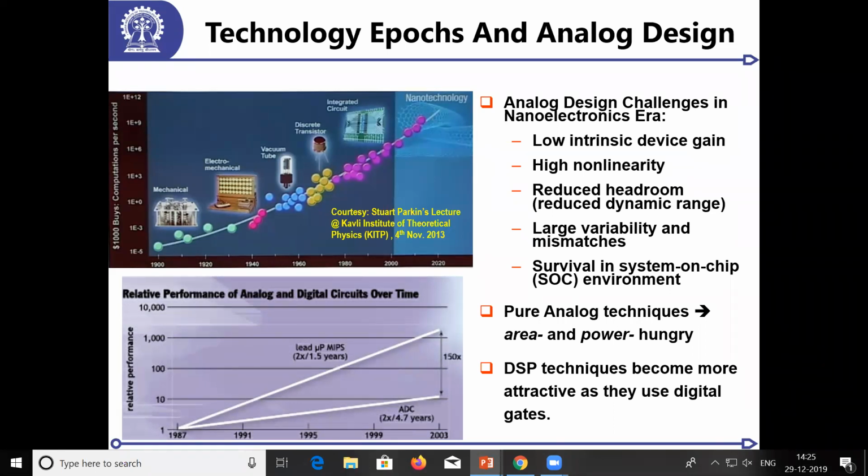Now, what happens as transistors scale is that they get smaller and smaller. For the same gm, we'll need a much bigger transistor in the older technology. Now, if this smaller transistor varies by a small amount, the percentage gm changes too much. That would cause a variation in either the gain or something called an offset, and that would lead to different performance degradation.